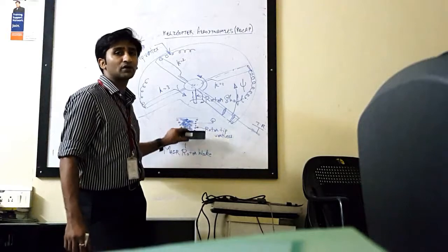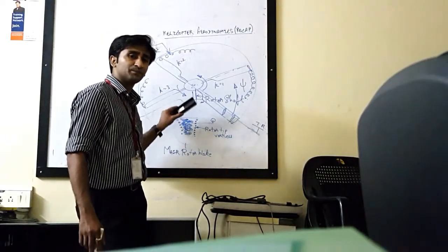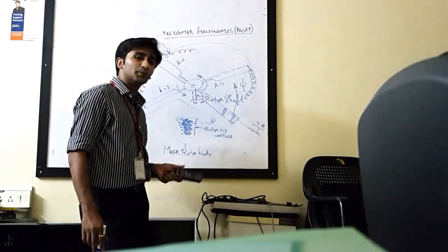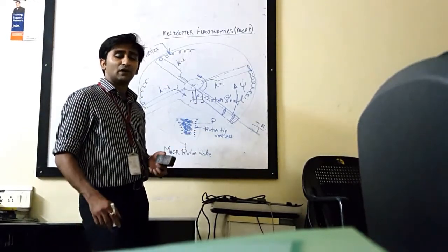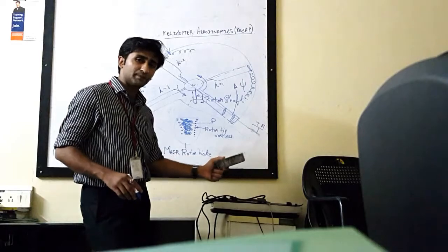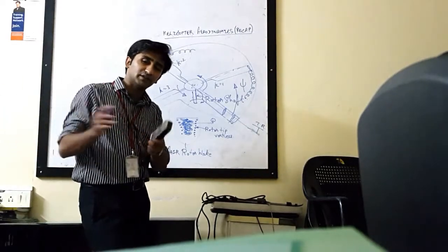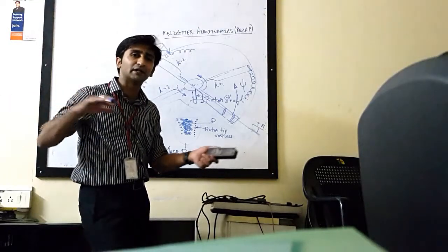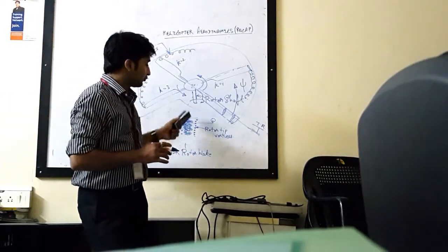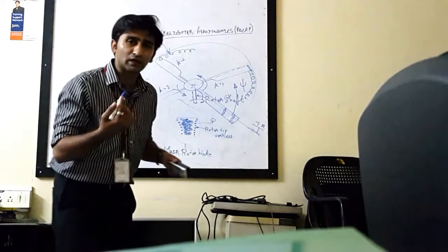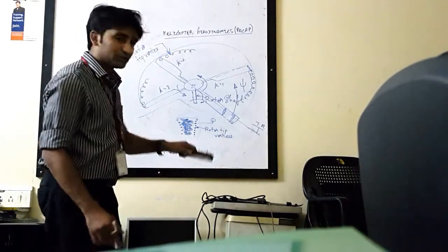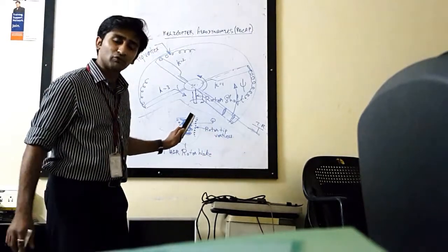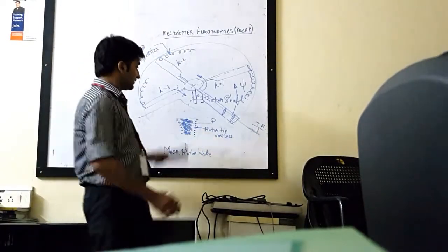Once the wake energy goes up, this wake becomes stronger in terms of the energy contained, and that is why, once a bigger helicopter passes by, a large amount of time is required before any other small aircraft can enter that space, because all these vortices would still be revolving around the axis even though the helicopter has passed. Right. So now we'll see what happens to these rotor vortices as the helicopter is moving.